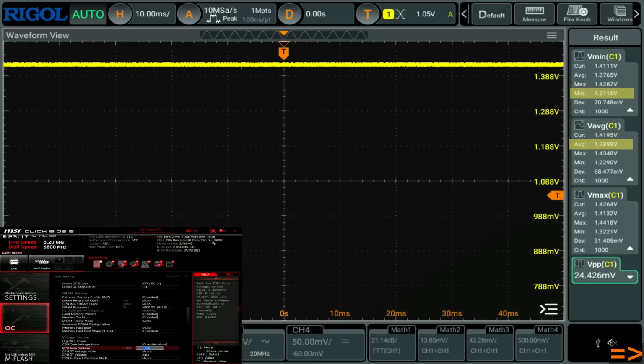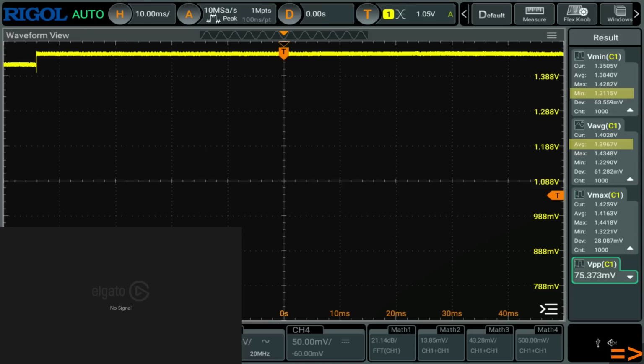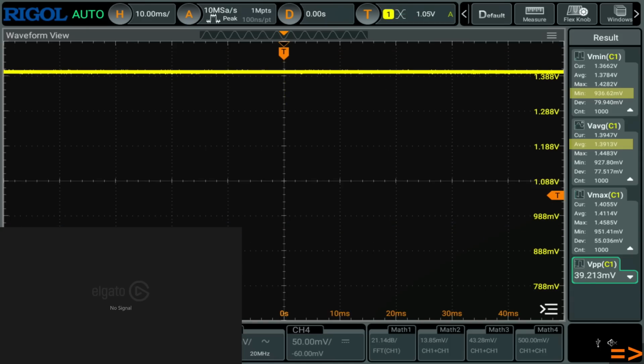So from 0 to 50 amps, we're going to have 0 V-droop, and then past 50 amps, we get the full mode 8 amount of V-droop, but offset by 50 amps. So 1.4 volts should be about right, I think. I might be a bit low. Well, we'll see. If I'm a bit low, we can add 10 millivolts or subtract 10 millivolts.